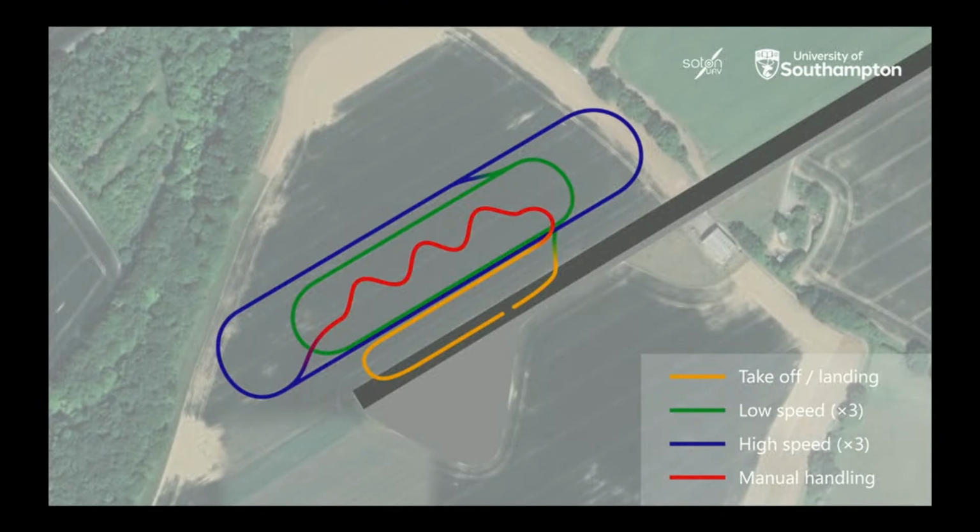And this is where we set the cruise speed as unfeasibly low as possible, and we essentially test ArduPilot's stall prevention feature. We deploy the high lift devices, and we attempt to do 3 orbits of that, depending on how windy the day is and how well they've actually made their wing to fly as slow as possible. We would maybe get less than 3.